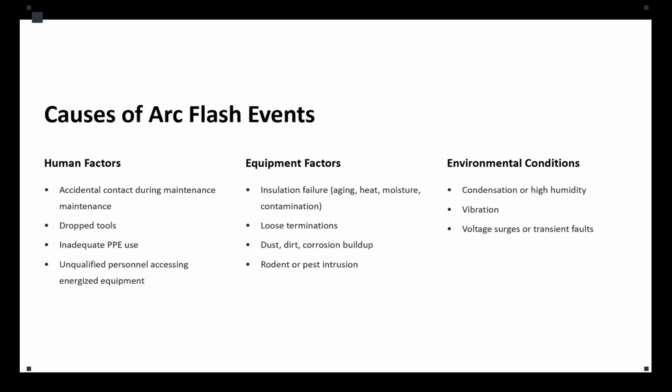Now, another factor is loose terminations. If we have a slightly loose lug or connector, which normally you may not consider a very big deal, it causes some localized heat. There is a specific standard for temperature rise for electrical equipment, especially power equipment.